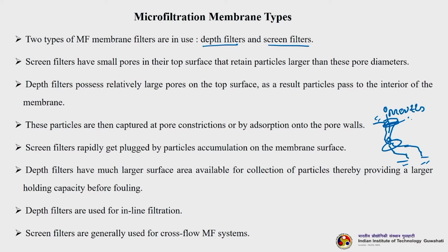Due to these constrictions, many times solutes pass through the pore but get retained on the surface inside the pore. Another case is adsorption. Let us say this is a pore. The small solutes are passing, but they are getting adsorbed to the surface wall.